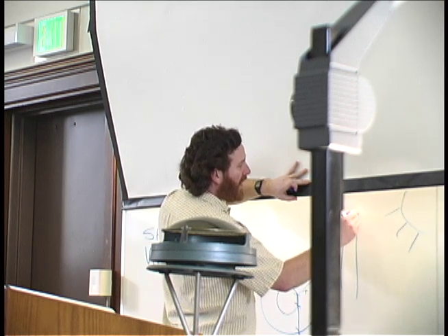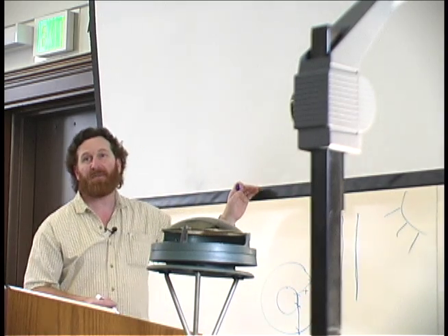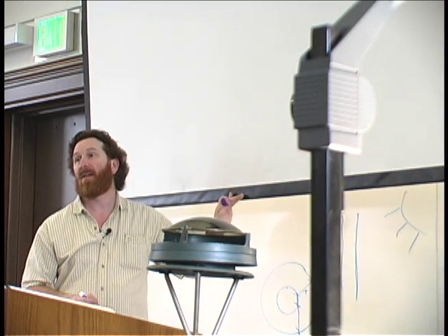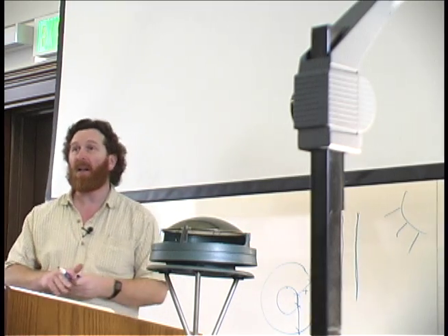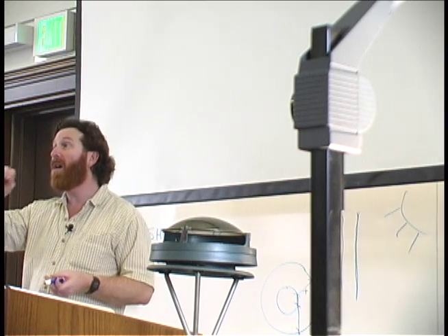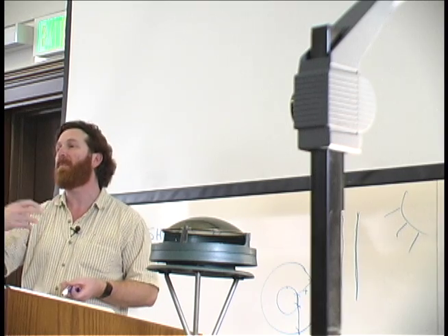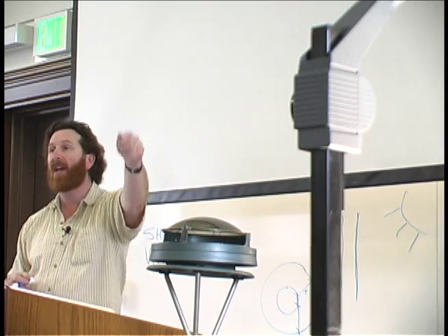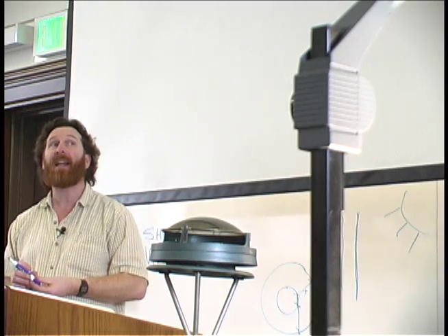So normal low E glass has a thin film of metal on the inside surface of the outside pane. That's low E glass. And what it does is this real thin film of metal will let visible light go right through it, so you can't even see it. But when that long wave thermal radiant energy sees that film of metal, it gets bounced back. So it stops the radiant transfer out through the glass. So if that were low E glass, now I'm not radiating to that building outside or the tree. So it really makes a big difference.